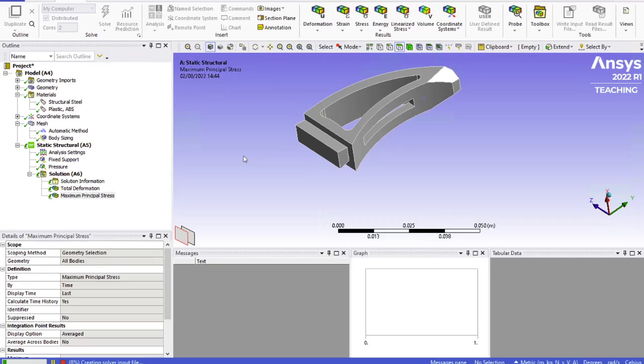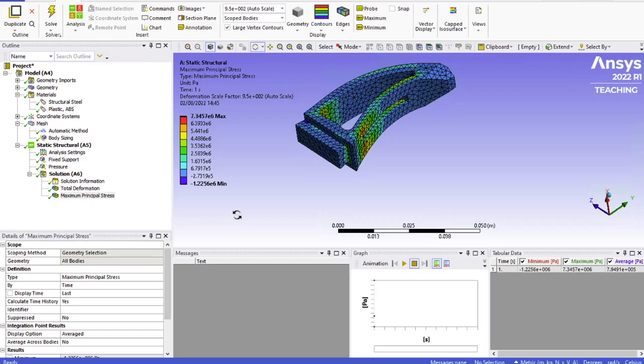So now we solve the problem. When we are solving, essentially what it does is that it is now using the geometry of the elements, and it is forming the element stiffness matrix, and from there it is putting it into the equilibrium equation together with the known members of the vector of nodal displacement and the known members of the vector of nodal forces, does the inversion of the matrices, and then finds the field variable, which is translations.